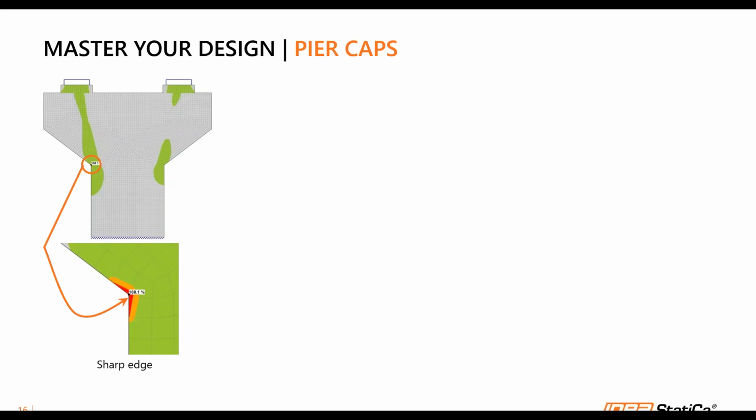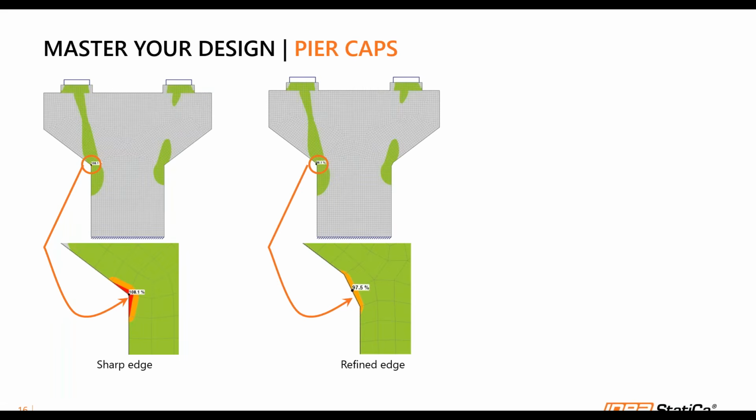So with that, we actually have some sharp edge. Those stress peaks would still be occurring. And if you try to refine the edges, it will make the mesh more refined, and you will have much better results for stresses in this case.